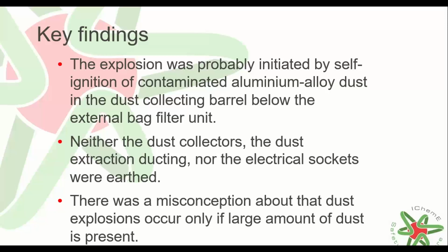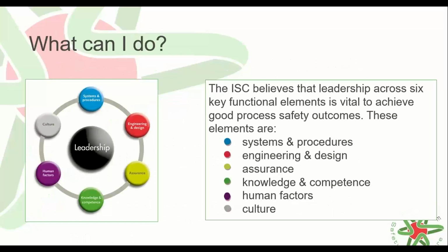case. And there was another misconception in place, that dust not visible in air cannot explode. Good housekeeping and periodic dust removal could prevent accumulation of combustible dust, which would reduce the risk of dust explosions. So there are misconceptions around dust explosions, and I hope that in the What Can I Do session, I can highlight some of those. If you have more in practice that you would like to share, then please feel free